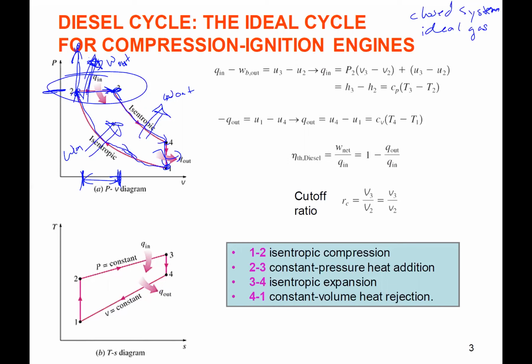Okay. So if we do the TS diagram, isentropic compression, constant pressure heat addition just changes that slope, right? Constant volume would have been here. Constant pressure just changes that slope on that heat addition, going left to right, adding entropy, decreasing entropy down here, so going right to left. Okay.